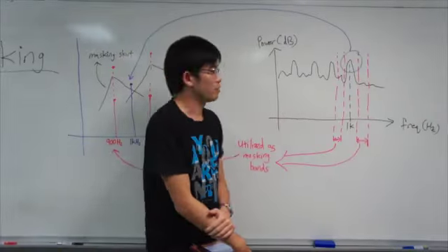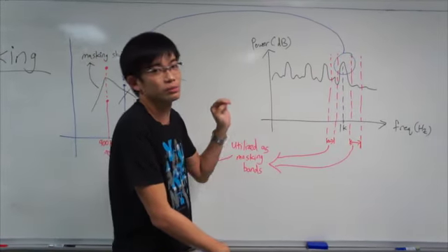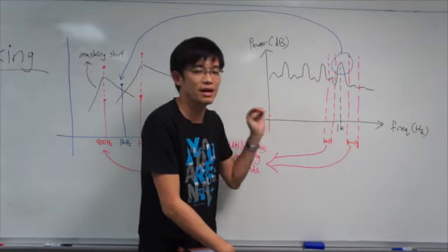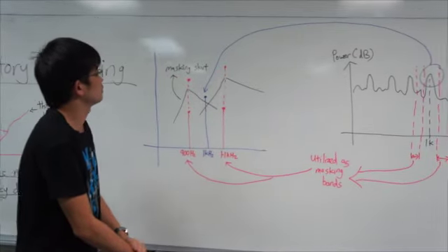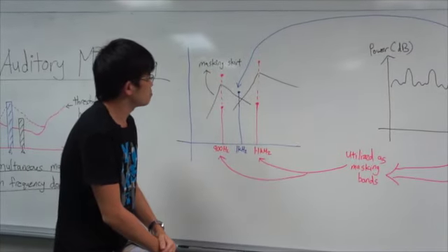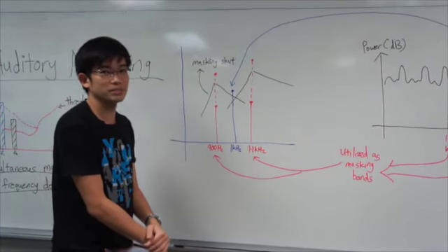To further illustrate our ideas, we choose 1 kHz tones as an example because the 1 kHz tones is also the most significant tones exist in the musical signals. So let us look at the masking skirt. In this diagram, masking skirt shows that it can mask out more higher frequency components than lower frequency.